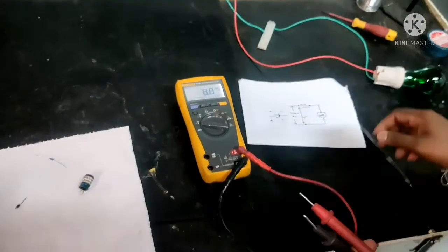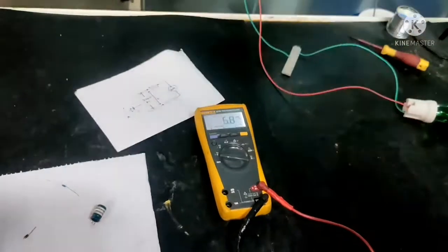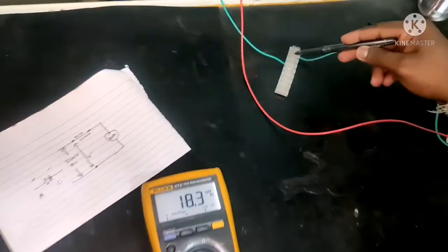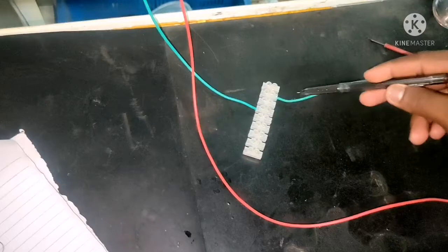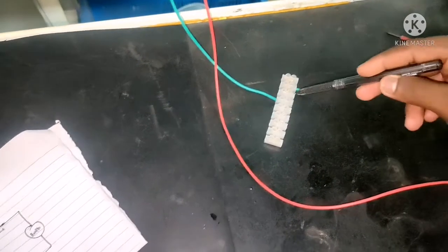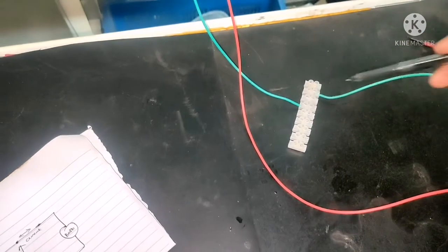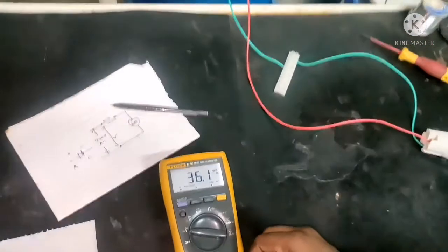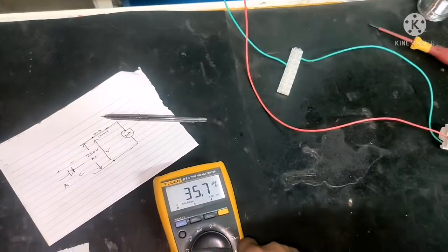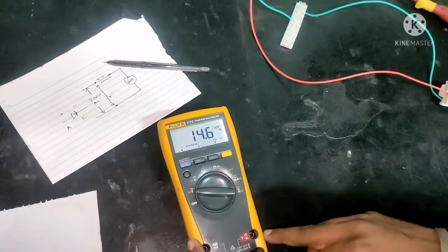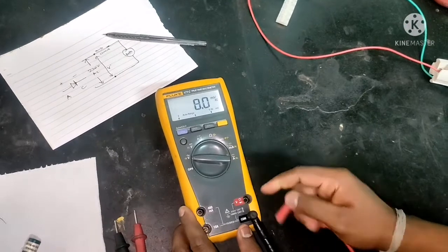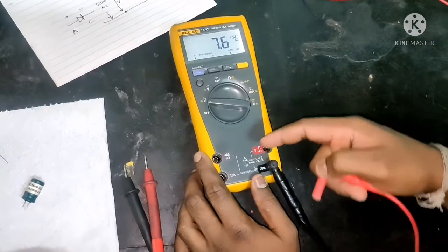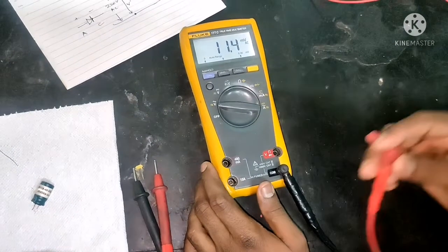As I told you earlier, for checking the current, you have to ensure that your multimeter is in current mode. That is, you have to change the selector switch to milliamps or amps. So now I am going to select it. I will remove the lead from this end. You can see very clearly the voltage, ohms and diode symbols on one side.